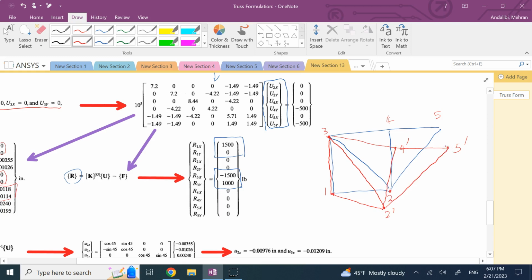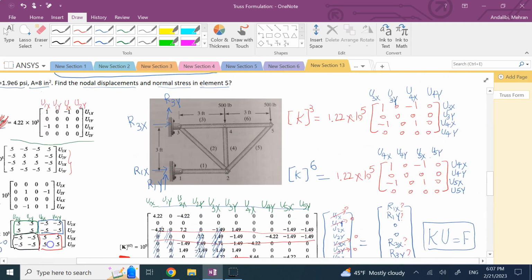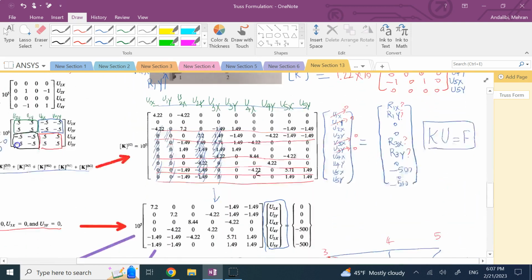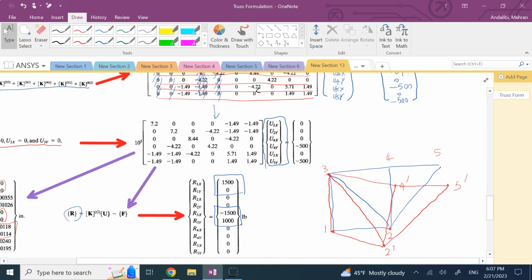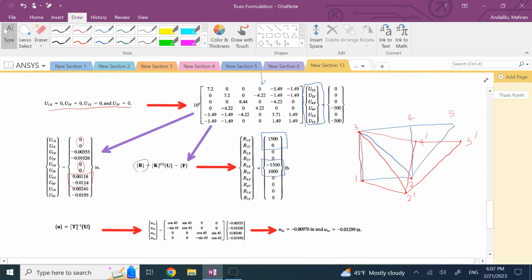This is the deformed truss in red. And again, this is done with a lot of exaggeration, okay? Does that make sense? Well, of course. With the pin down at nodes 1 and 3 and with these forces pushing down, of course the truss would go down. So if you see a displacement that doesn't make sense physically when you draw the deformed truss, know that something is somewhere wrong, okay? Always do a sanity check.